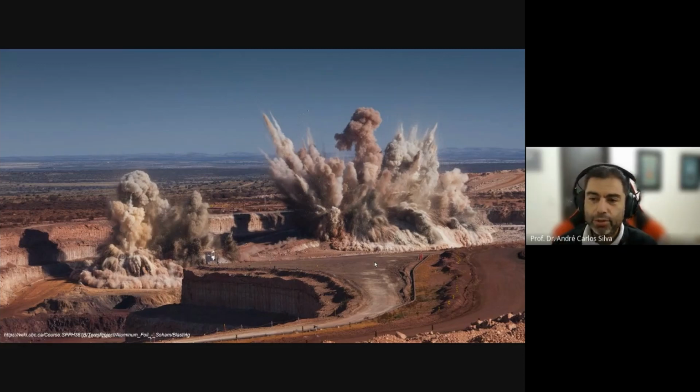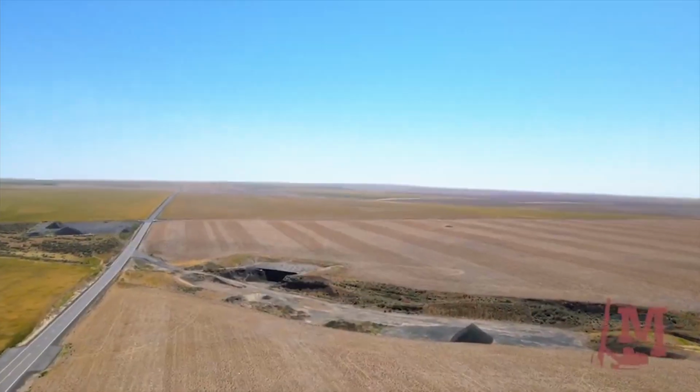If you see something like this, it is actually not a good blast. You have a lot of gases going up. We don't like this. You're actually losing energy by doing this, and you're projecting material, so that's not okay. If you take a look at the video and again at this picture, you're going to see the difference. This one has a lot of material going out, so this is just showing off. You don't want to have this, you prefer to have things like this.